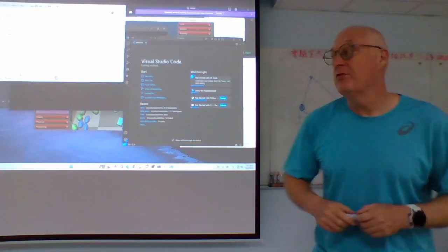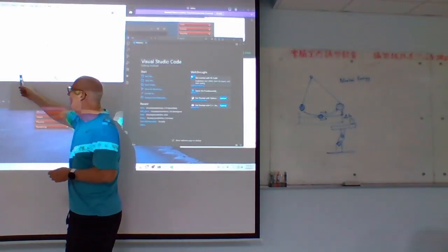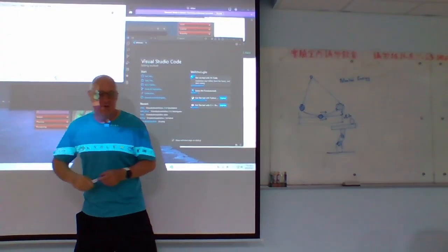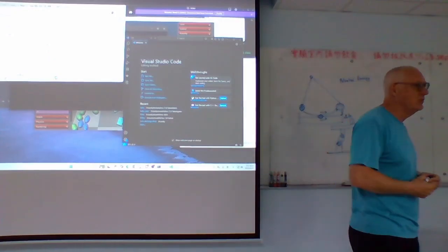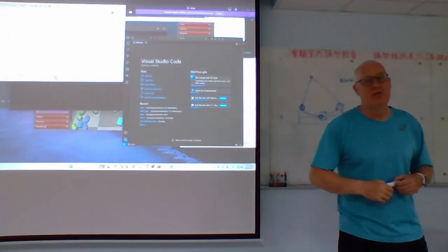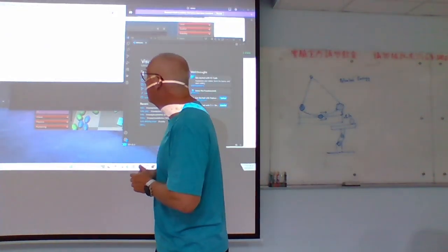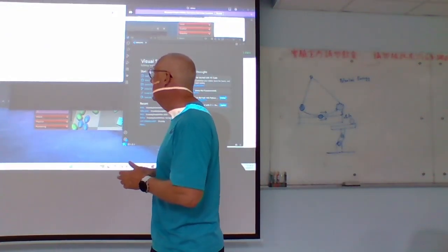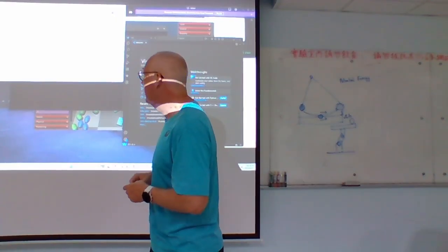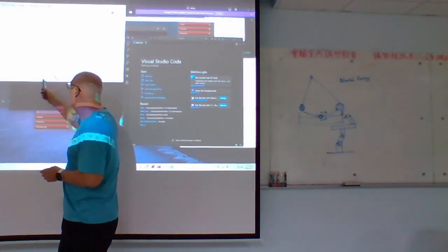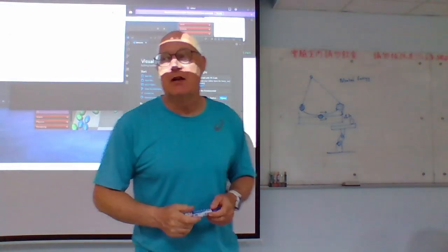But of course, looking at the timestamps here, the more often you do your update, the more accurate your simulation usually is. But it also runs a lot slower. So running from 2 milliseconds or 10 milliseconds to 0.1 milliseconds would be a factor of 100. So there, your simulation would be 100 times slower than if you run it at 10 milliseconds.